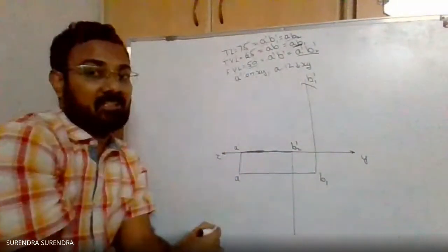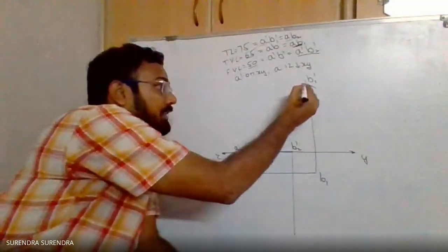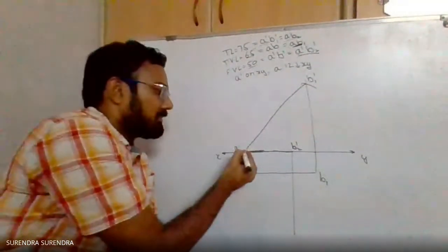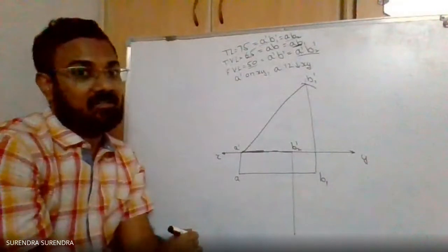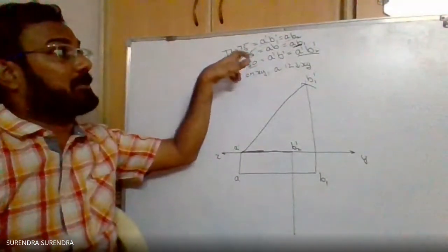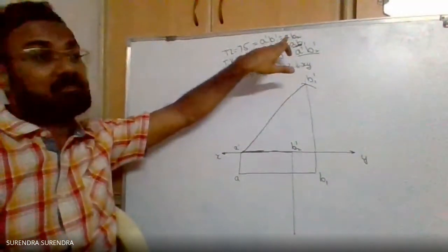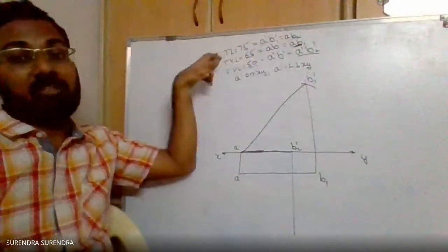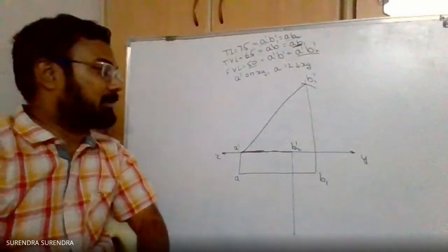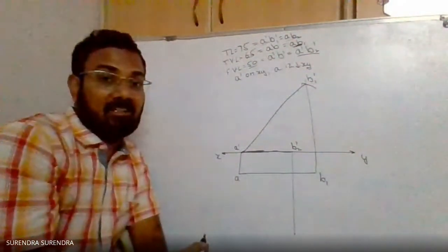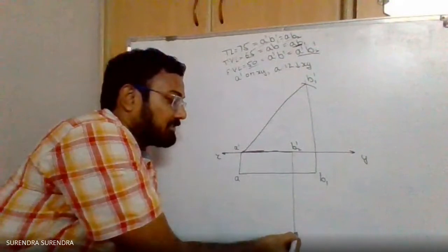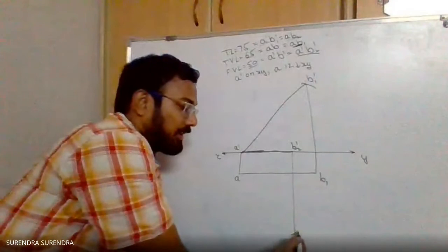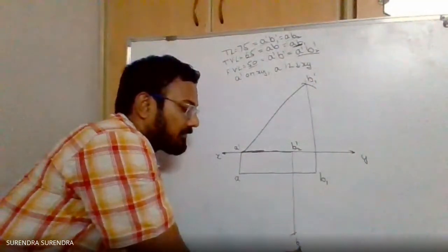The length of the line is given. So join A dash B1 dash. Similarly, 75 mm radius, so AB2 is also equal to 75 mm, true length of the line. AB2 is also equal to 75 mm length. So with A as center and 75 mm radius, draw an arc on the projector from B2 dash. We will get point B2.